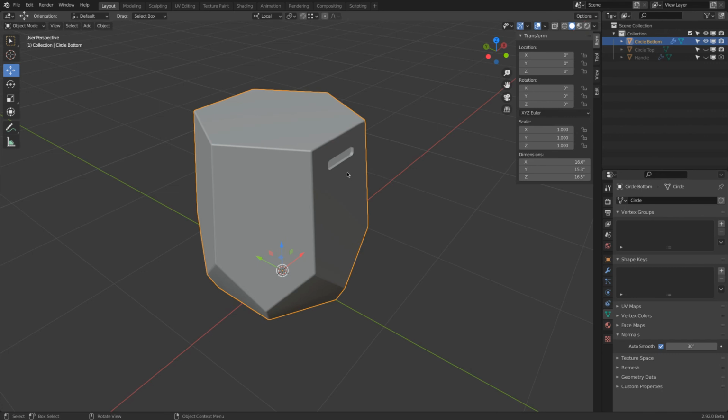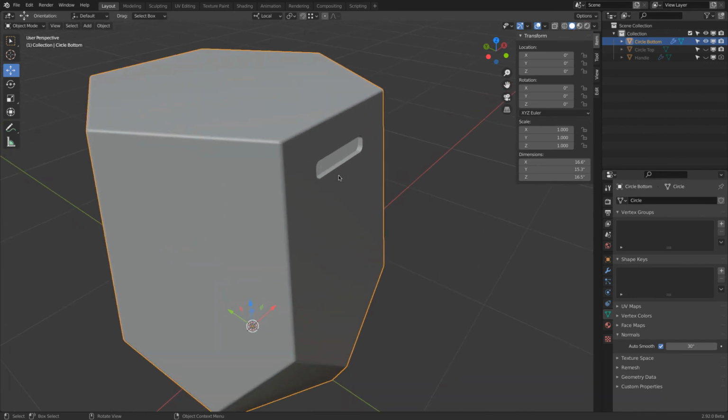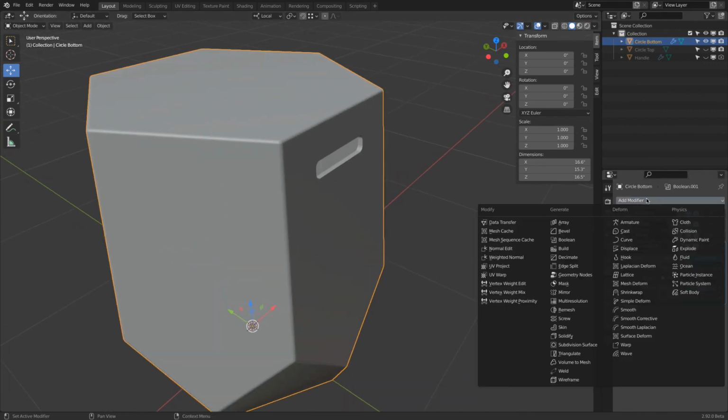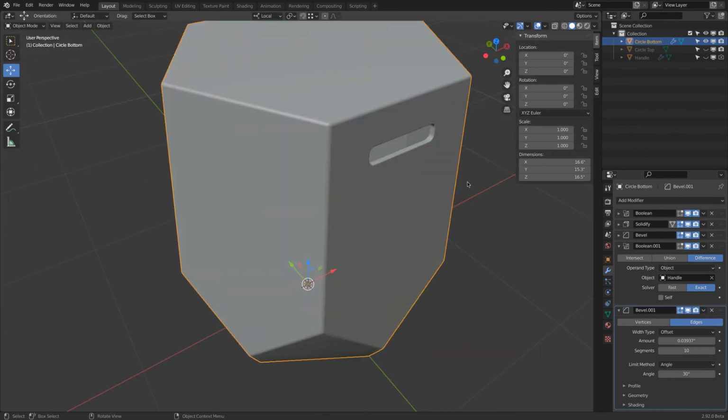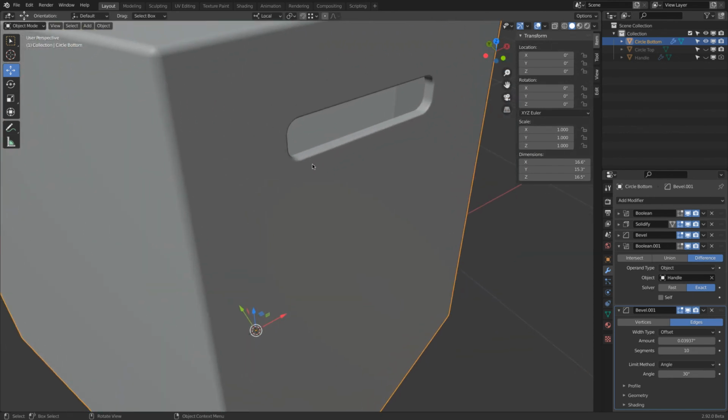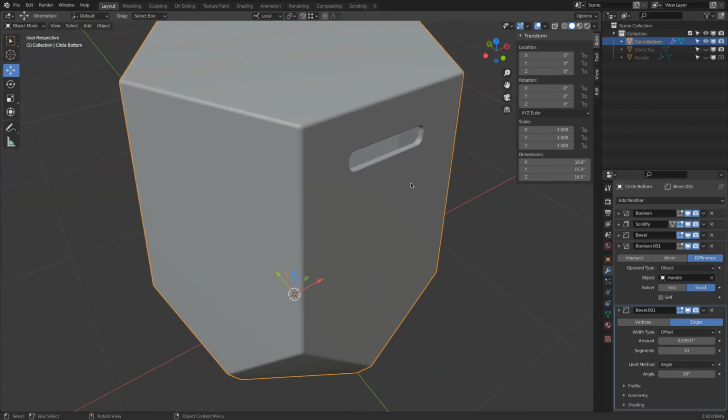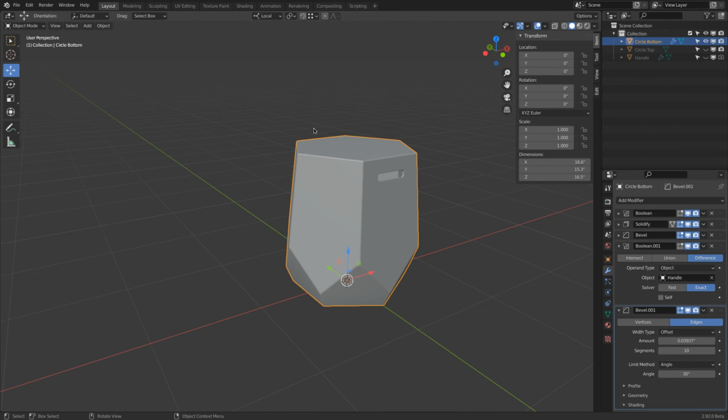To make this a tick more comfortable, since this is a sharp edge, we could go ahead and add now a bevel command, 1 millimeter, only 2 sharp edges, 10. Yeah, there we are. Now you can see how this is nicely rounded. Okay, very good. That's it.